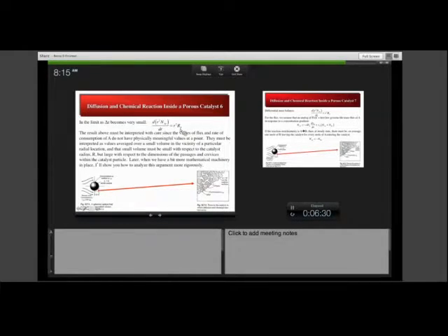And so the particles are essentially always behaving as if they're seeing a steady state or pseudo-steady state environment around them. And so if we take our mass balance in the limit as delta R becomes small, we get the result that is shown here, where RA is the net rate of production of compound A. And here's something that I want to point out to you that is fundamentally different from what we've done before.